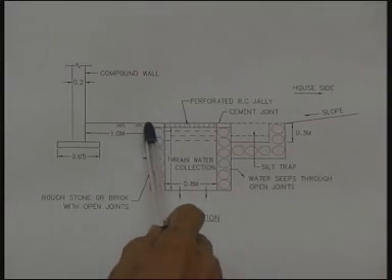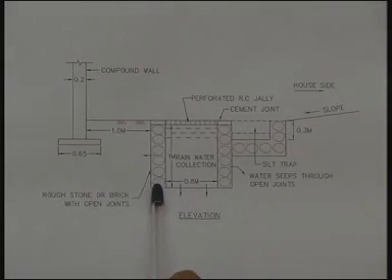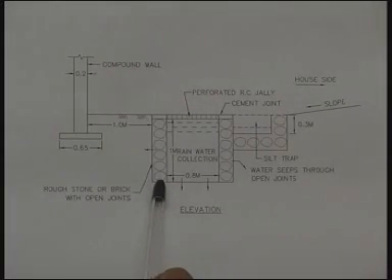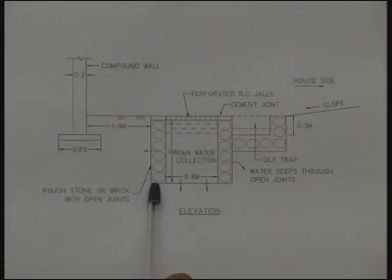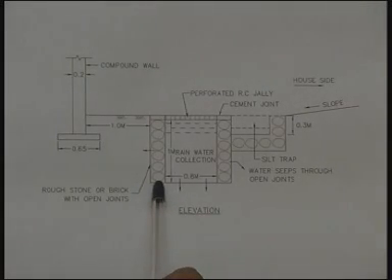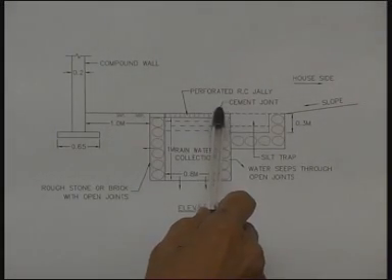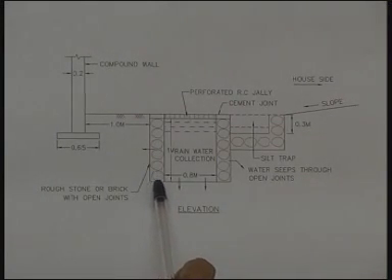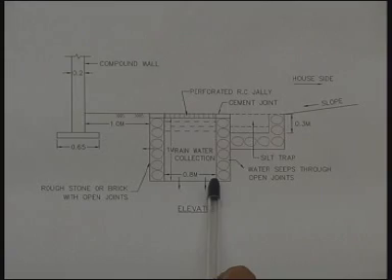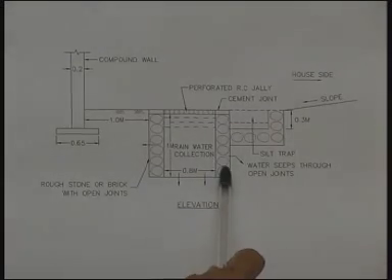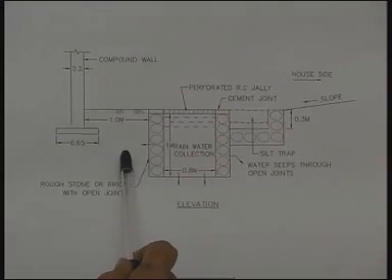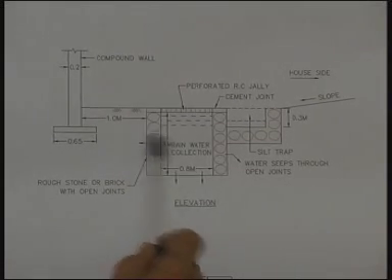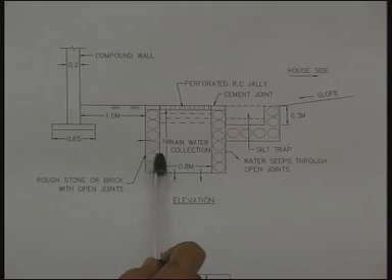and in order to retain the sides of the trench, rough stone dry packing can be done, something like a revetment, a vertical rough stone dry packing. If the soils are loose, it can even have a slight slope, and there is no revetment at the bottom. This revetment is only intended to hold the soils so that they do not cave into the trench,